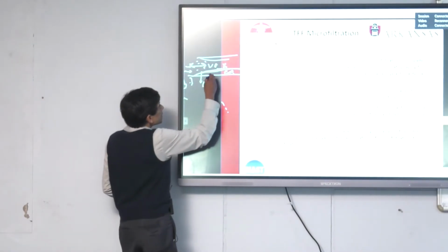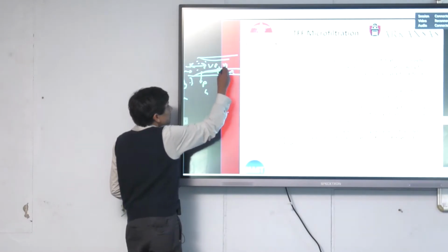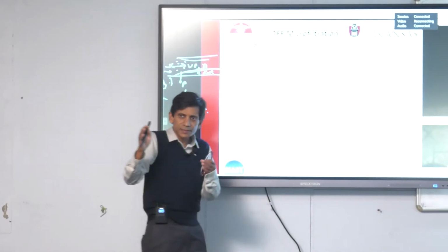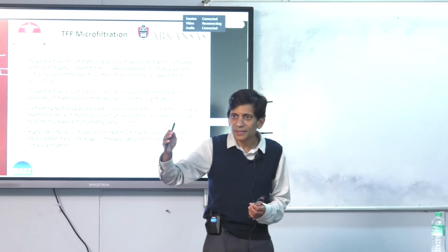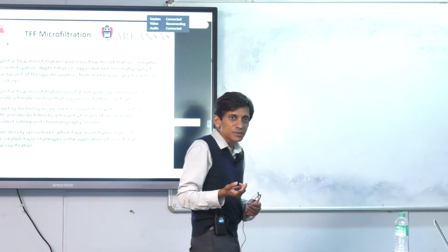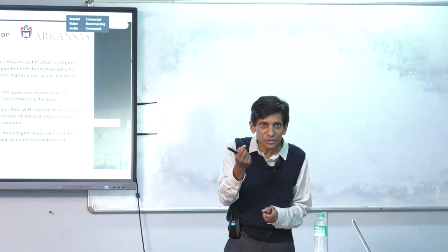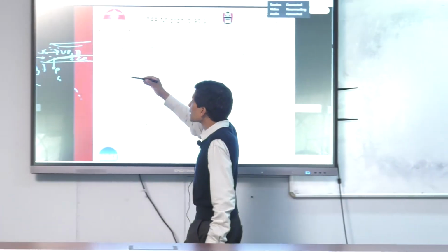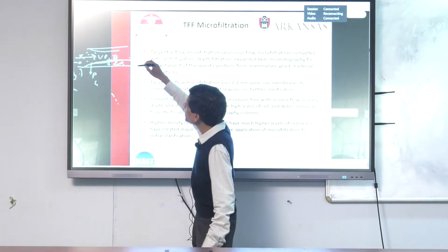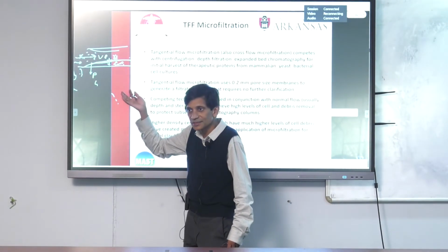Let's say that you have convection towards the membrane and you have back migration, because obviously if something is coming, it's got to be moving away, otherwise it's going to grow forever. Now, if we think of diffusion processes, we say diffusion is driven by a concentration gradient, right? So we would say, okay, the concentration is higher here, it's lower there, so we can define a back diffusion coefficient, a diffusion coefficient away from the surface.